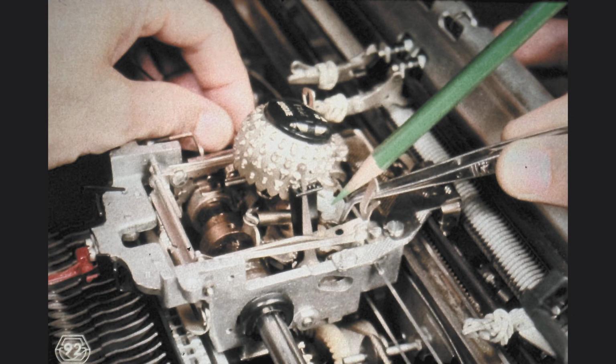In order to grasp the right end of the tilt tape with tweezers, as shown here, you may need to feed some of the tilt tape into the carrier with your left hand to build up enough slack around the pulley. Once you have removed the tilt tape from your machine, it is time to reinstall it. Simply reverse the order of the steps you used to remove it.